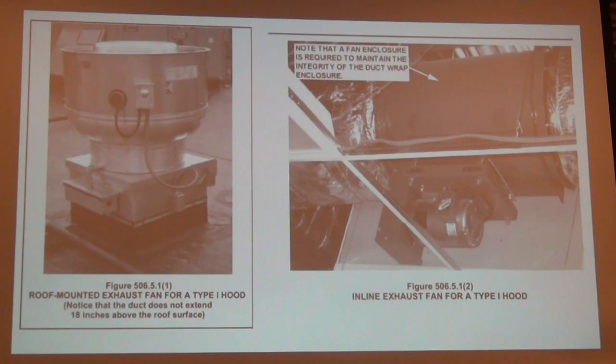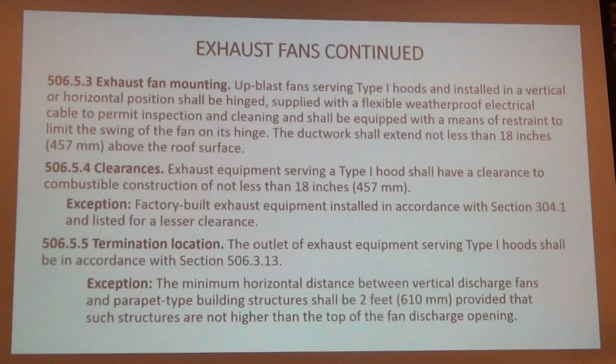Because if you wrap the motor, I have a concern that the motor might not get proper ventilation and might overheat, and we're causing more of a fire hazard than if we left it unwrapped. Exhaust turbine, type 1 shop with clearance to combustibles at 18 inches, so that's the same. And then the termination, we already went through that.